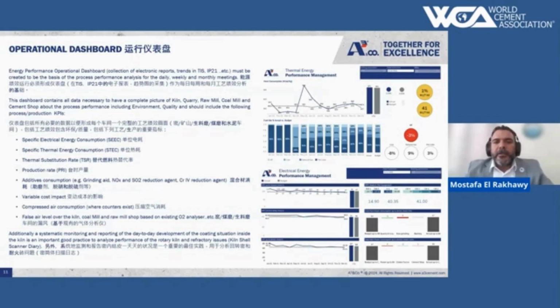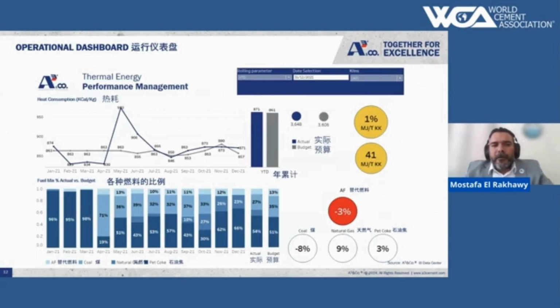systems or technical information management systems, and there is also a lot in the market who is providing these systems. And then, this plant, for example, which we are showing, is showing its data on a dashboard on BI tool, or even on Excel tool. The most important here is to identify the parameters you will monitor, and to have this data automatically on daily basis, weekly basis, and make energy performance management meetings and analysis to identify where you are from the target.